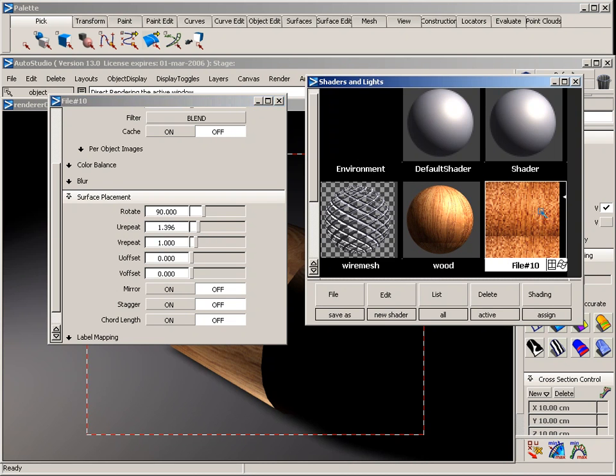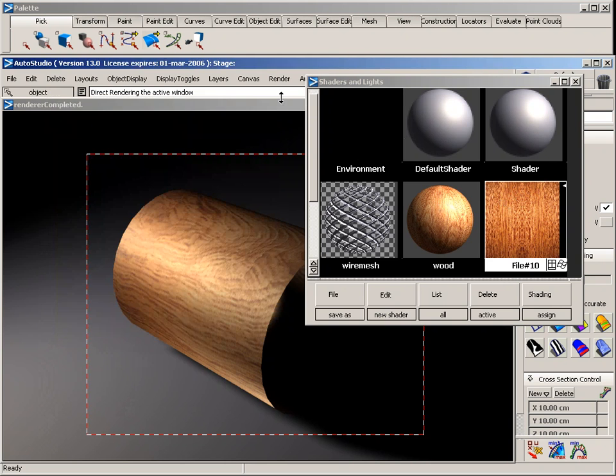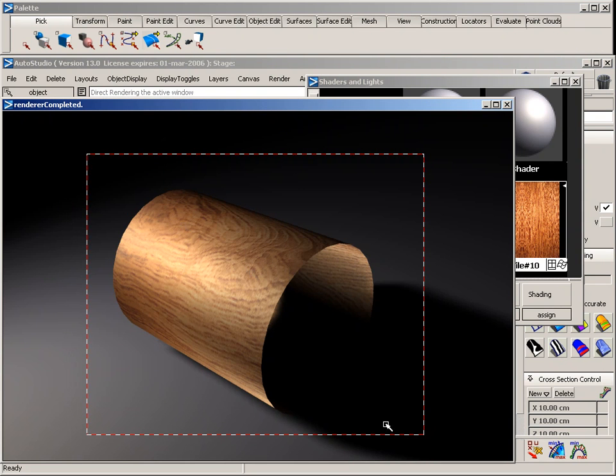You can see this probably better if I increase the resolution here. So in my particular case, I want to repeat the V direction by 2. This will likely give me a seam down the center. You can sometimes hide that seam if you choose to mirror that texture. If you look at this here now, it's mirrored over to the side, so hopefully I will not be able to see that seam.